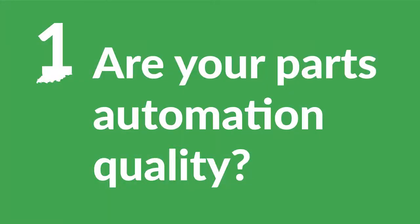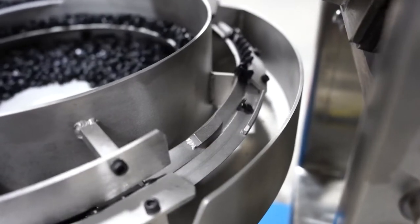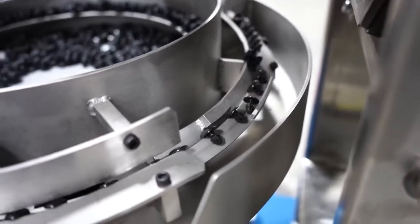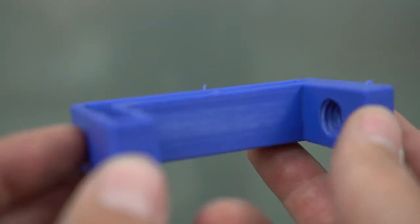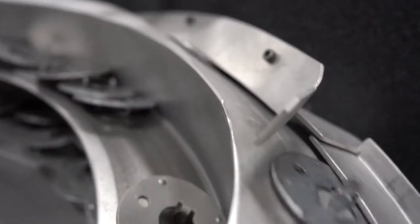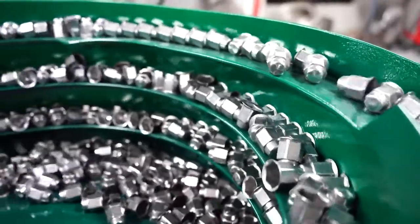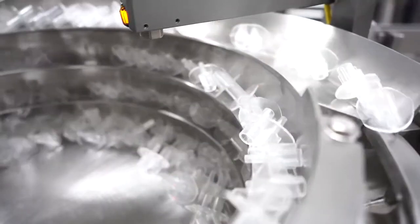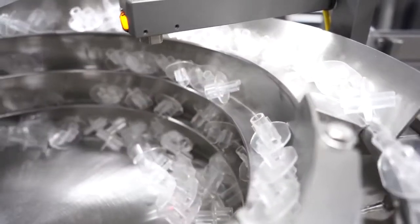1. Are your parts automation quality? If you have multiple suppliers and production molds, it's important to note how much variation there is between parts, as these variations can add complexity to feeder solutions. Another factor is material flashing issues or plastic pieces that hang off of some or all of the parts. To be a right fit for a feeder application, it's important to have a consistent part. Take care to communicate mold release coatings, lubricants, and any other substances that might be left on the parts. Seemingly minor variations in production parts must be carefully accounted for when designing a successful vibratory feeder system.